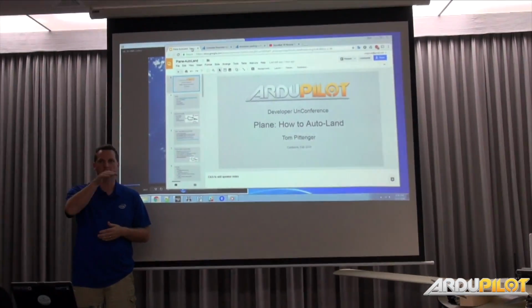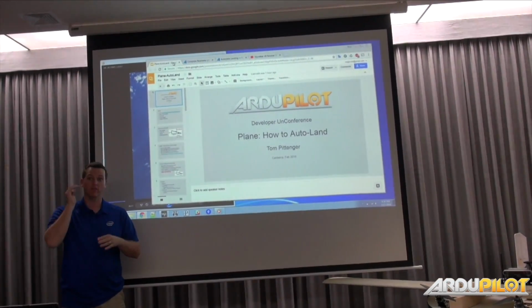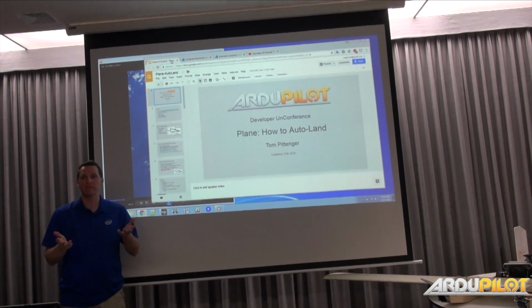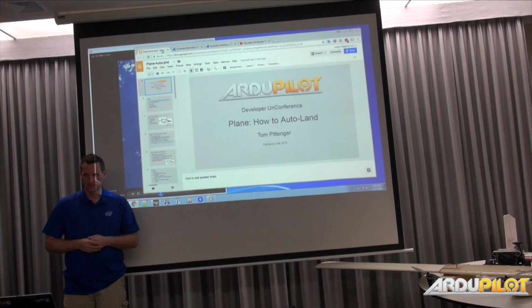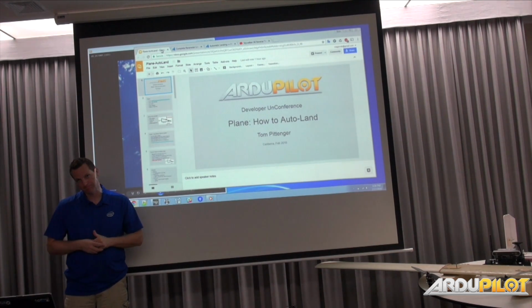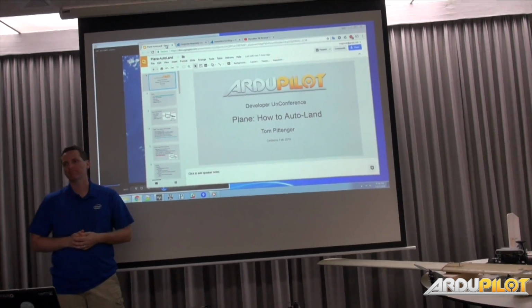Yeah, for a very efficient aircraft like that, we have a really nice shallow glide slope. It's really good for efficiency for long flights. Then it's hard to bleed off that speed when you're actually on land. So this is where they went. Yeah, those spoiler things from Hobby. That's the idea. But again, for 3 hours, he's lugging around more weight. There's always that trade-off. That increases stall speed.